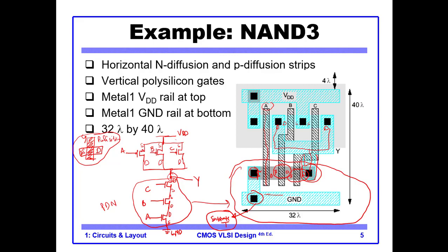Okay, so this one is again transistor A, and it is connected to the VDD. This is again the N well tap, so this is the fourth terminal, and then the VCC is connected here. So you see the source of B and the source of C, they are both here. This is important to understand. They are both connected to this point, and they are both on this side. So this is how a NAND gate is formed.